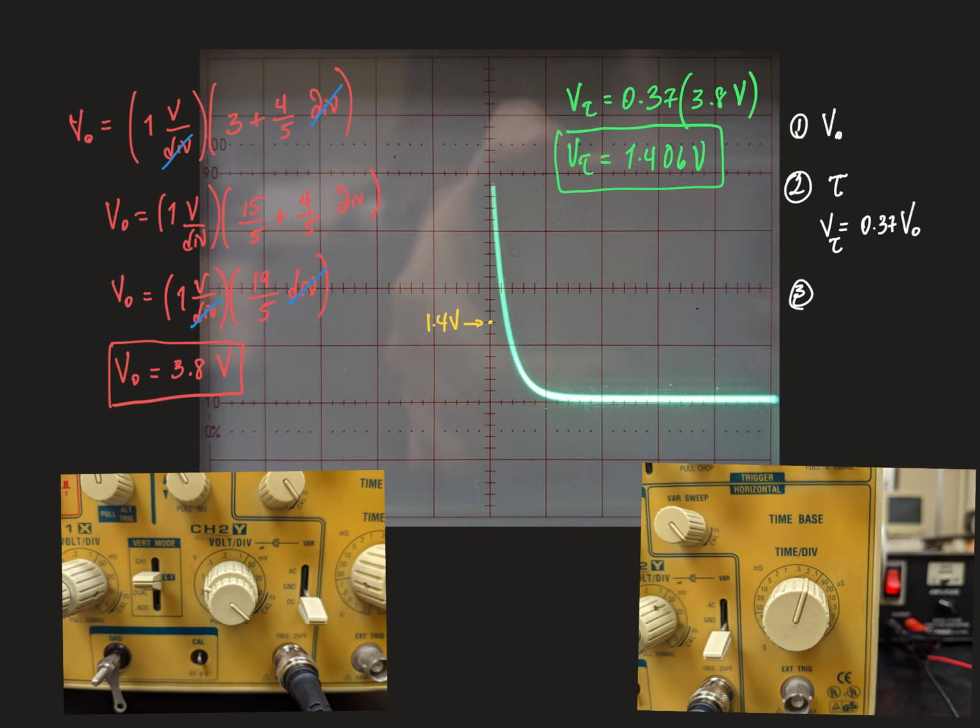All I have to do is move in the horizontal direction. And now I know that this is the voltage of 1.4. Now move in the vertical direction, and you can see that this almost happened there. All we have to do now is determine that time. How do we determine that time? Well, the horizontal division says that each subdivision, each square, is going to be 0.2.